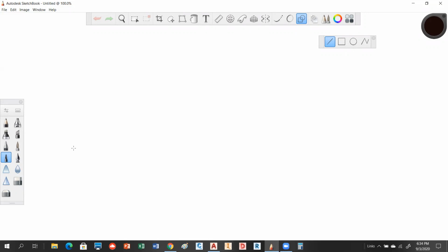Anybody take a guess what the maximum value for a polygon would be? 250. That's a pretty good guess. It's actually quite low. Theoretically, mathematically, it could be infinite, but if you had an infinite number of sides, you'd essentially have a circle. So AutoCAD does have a limitation. The limitation is 1024, and that number is a binary number, 2 to the 10th. So you can go from 3 up to 1024.